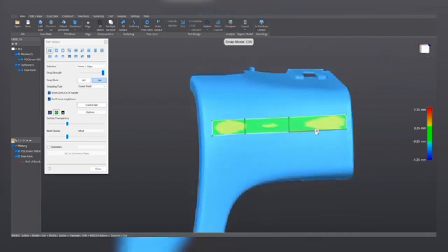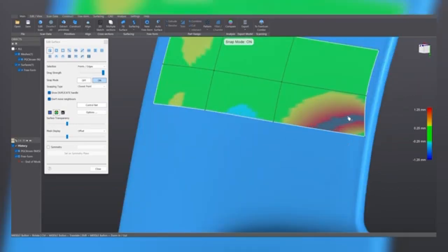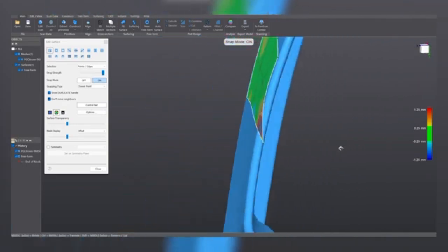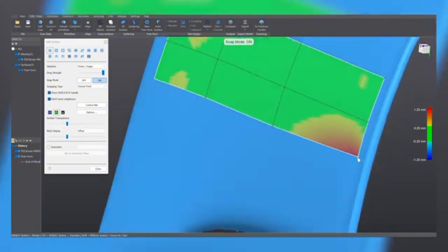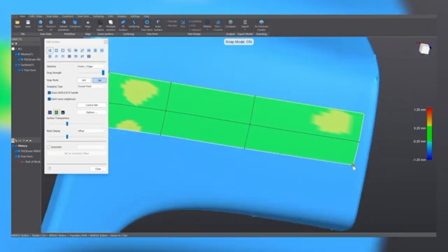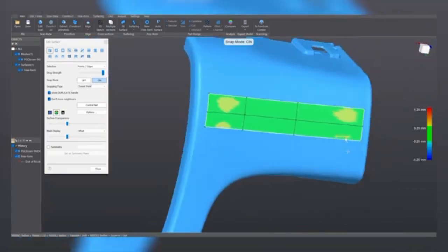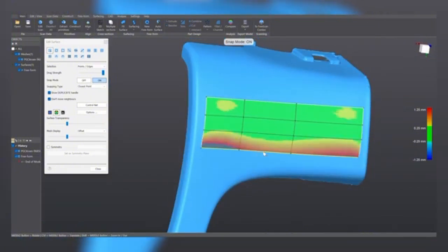Okay. To extend an edge, you can double click on it. It turns yellow, and then with the D handle, you can extend the surface. Now, if you observe some unexpected high error like this, it's because the surface is snapping on the other side of the mesh. So you can simply correct it by moving it a little bit, and it will snap onto the proper surface. Let's extend this one here a little bit more.